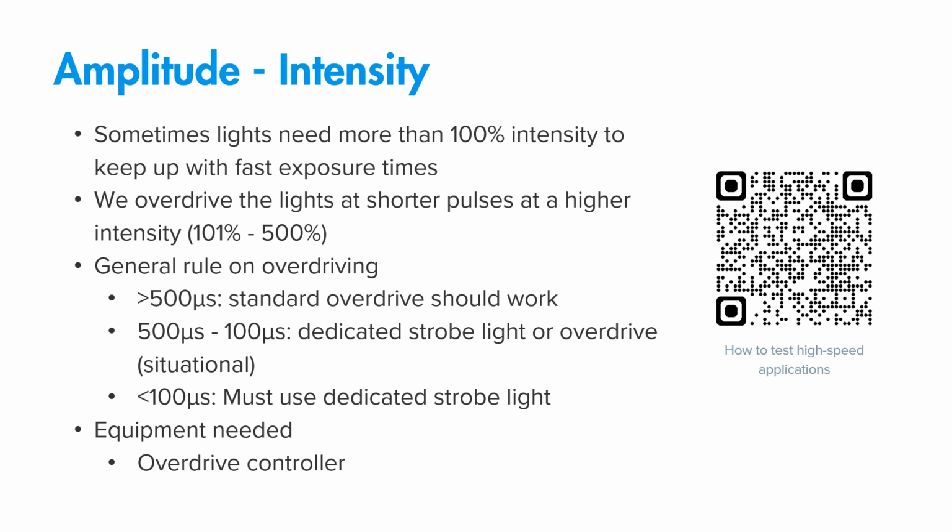So how do we know when we need to overdrive, and when do we need a dedicated strobe? That comes down to the exposure time of the application, as the general rule. So if your application's at around 500 microseconds, for the most part, standard overdriving should work.